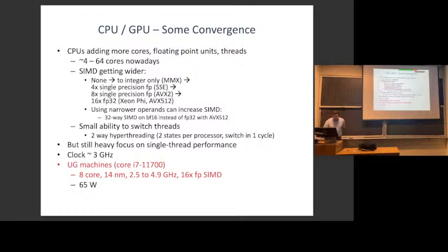If you use narrower operations, so there are 16-bit floating point representations, and there are 16-bit integers, obviously. Something that's 16-bit, the same data path can do twice as many operands. So if you use narrower data widths, they've also put in circuitry in the processor so that your SIMD gets more SIMD.